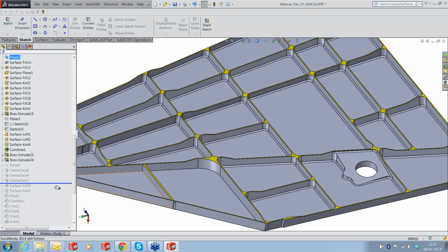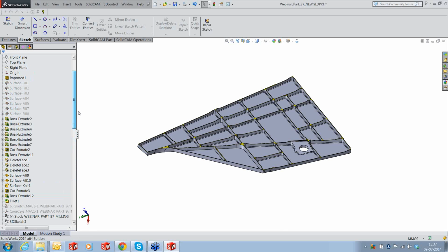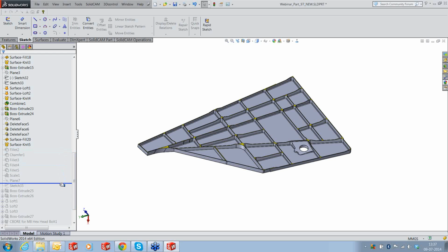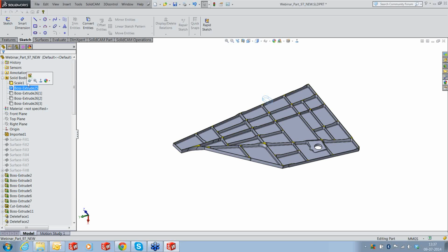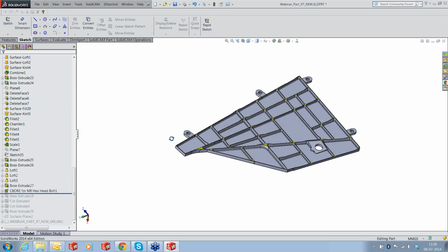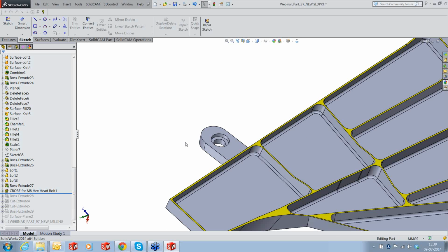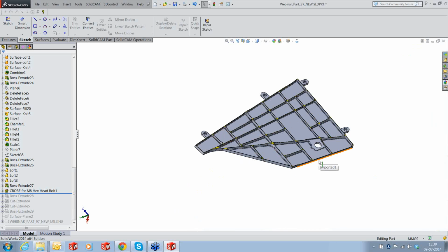Okay, from here we actually created, once we had the part, we created the lugs. We'll move it down, and you will see that we have got lugs up here that are getting created. So I'll keep showing you the lugs. The holding lugs. Counter bore, where we created the counter bore to seat an M8 screw into that. So this entire block will be then screwed down to the plate below.